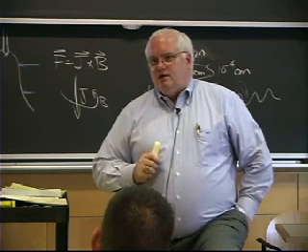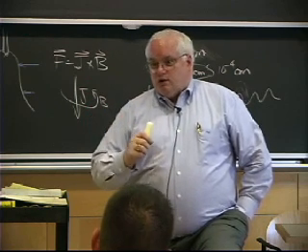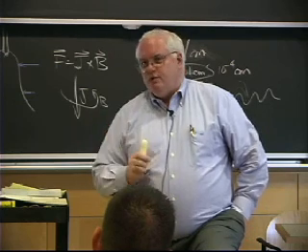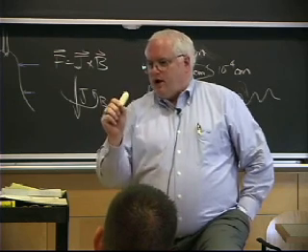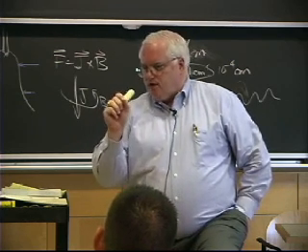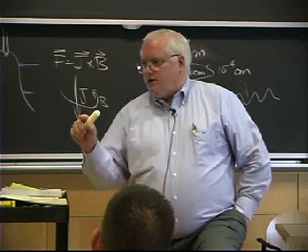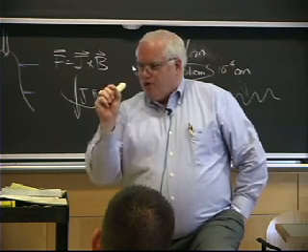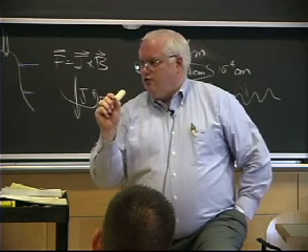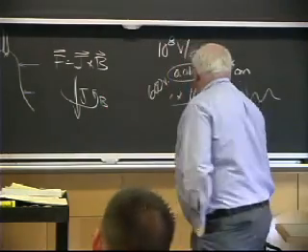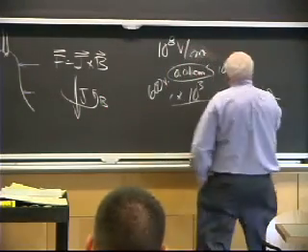And all of a sudden the engineer that worked with him says, well, we got these SEM photographs. Actually, maybe he showed me the photographs first. But in these photographs, in some of these spots, they had gone in and cut out the things, and they had found where they had cut into an aluminum oxide inclusion in the aluminum. And it was a very sharp angular inclusion on an atomic scale. Very, very sharp. So it wasn't just some rough machining thing.